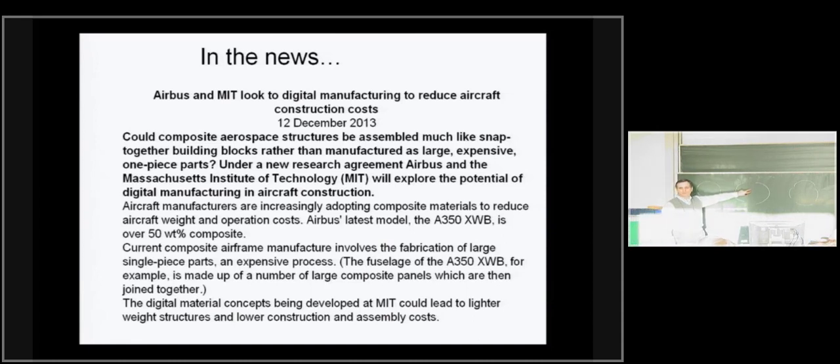How about this one compared to this one now? Remember, we said the fewer the parts, the better, because the assembly is less. But we already said that if we make them too few, the risk is high. So obviously I have two extremes here, but there's one more reason which is related to one of the words you mentioned. I make one half here and another half there, which presumably are identical.